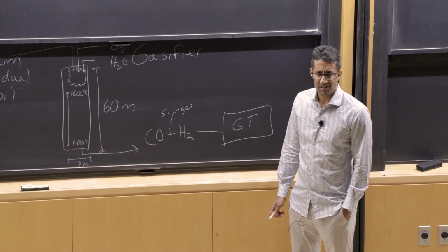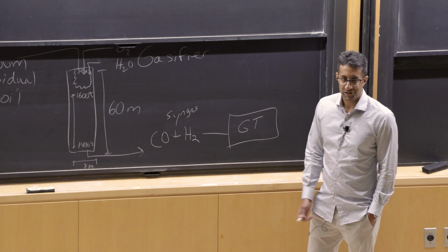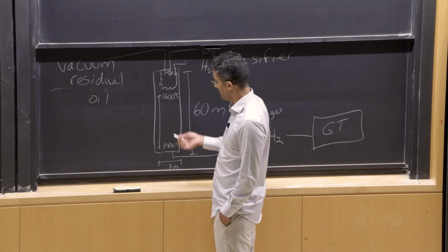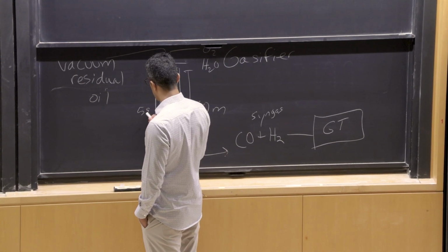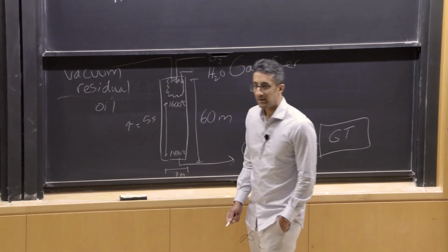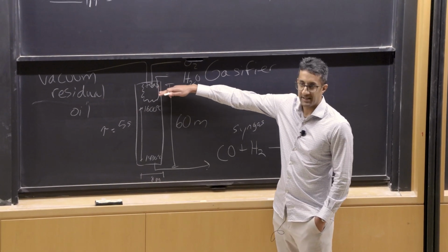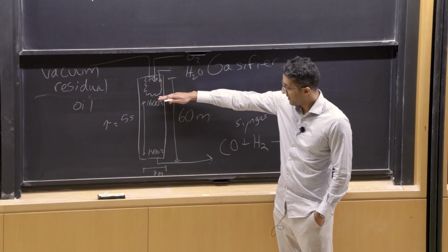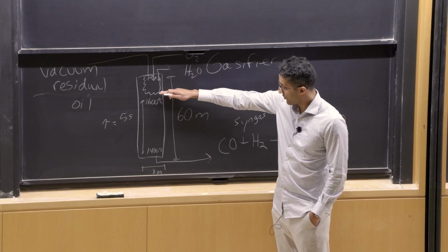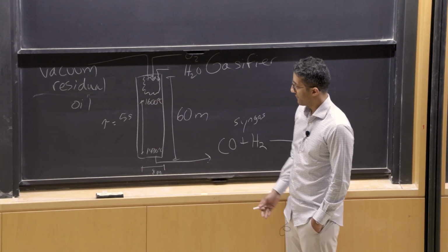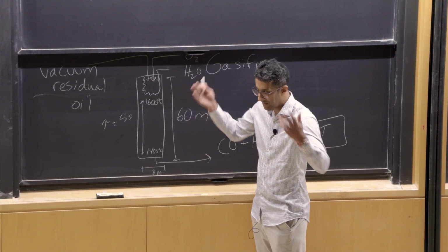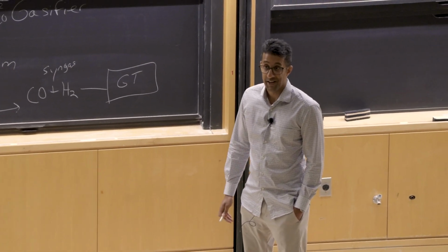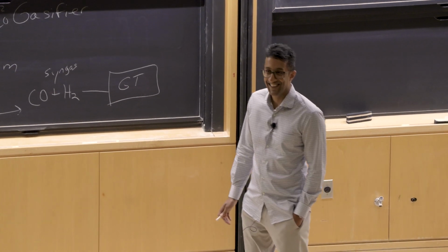And the plant engineers said, this is all a waste of time. We use equilibrium and it's good enough. Yeah? Because this thing here, 1600 to 1400, you can see, it happens over like 5 seconds. Yeah? So indeed, everything that's happening at the top is kinetically controlled. But then you have some intermediate products that are formed, and then your VRO starts reacting over this like 5 seconds, say 50 meters in length reactor in a homogeneous environment, and they just use equilibrium to calculate the final gas composition, and it's pretty good. It's actually almost as good as the kinetics, yeah?